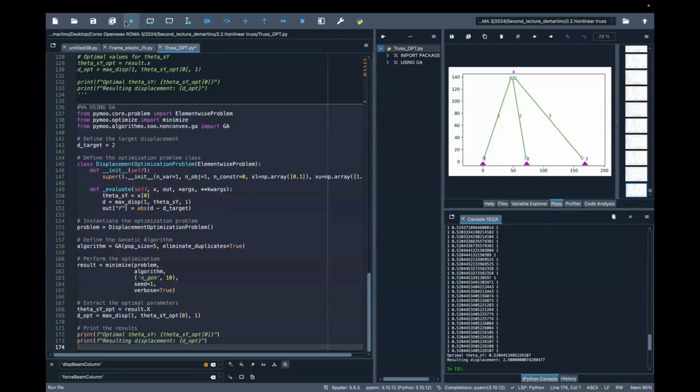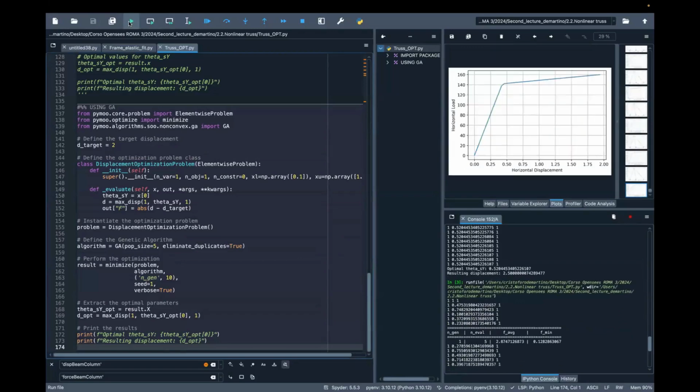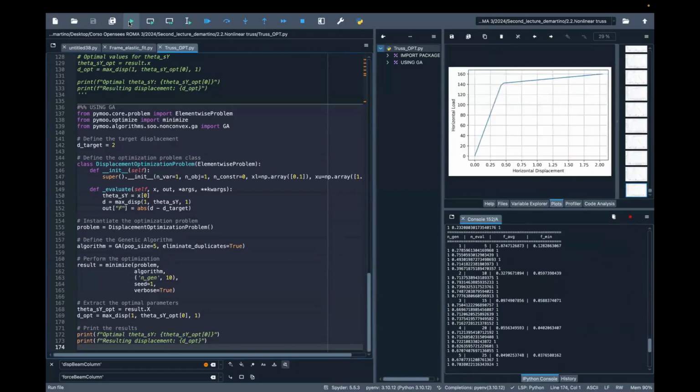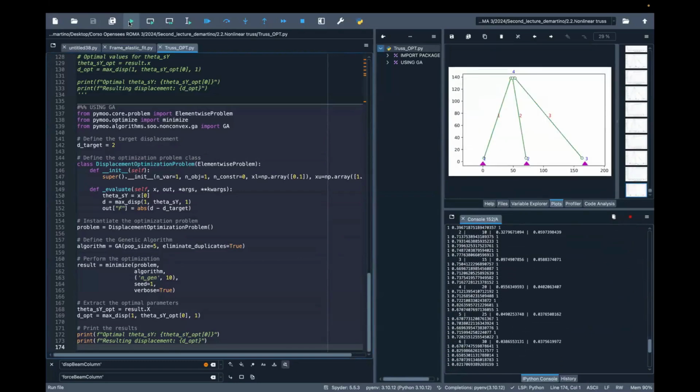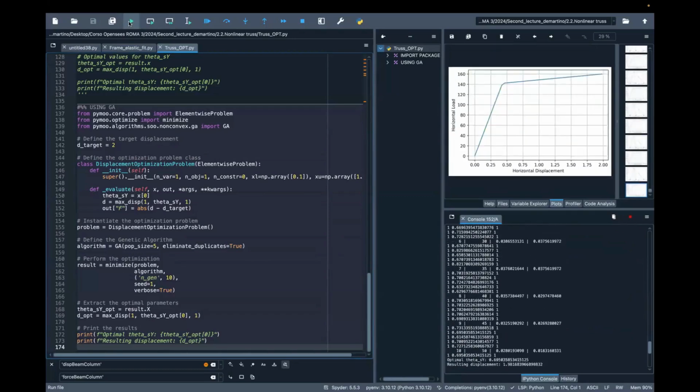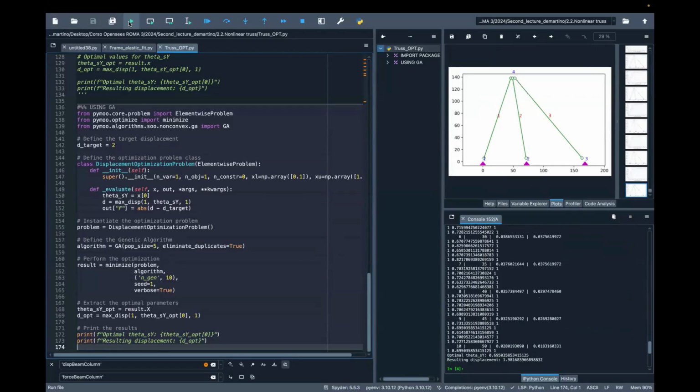You can write your specific code. Again, you can recognize where your function is used. This max displacement is used here, right? And this is again your goal function, exactly the same as before. And in this case, I'm using a population size of 5 and 10 generations. That's not important. If I run it, you can see that we finished the first generation with 5 kids. We have the second generation, 15 kids, 20 kids, 25. And then you can see we reached 0.69.